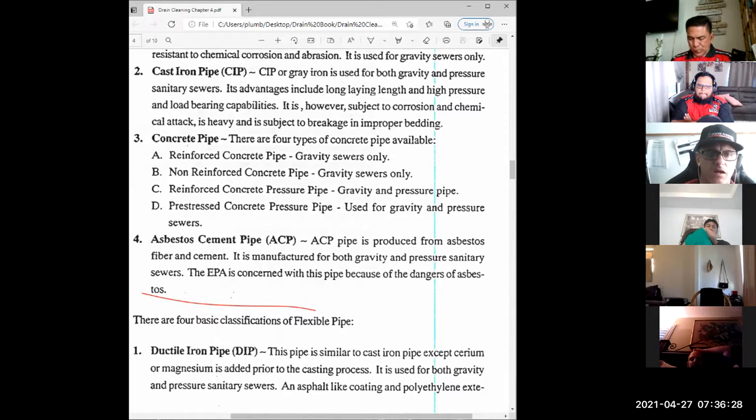We deal with it at Kahumanu Shopping Center. They have it as a water main. They have a 6-inch asbestos water main that fails from time to time. And it was a pretty big deal that we had to deal with a while back. But it is something that you have to contend with every once in a while, and you've got to know how to deal with it when you have to. But properly, you're supposed to just abandon it and leave it in place.